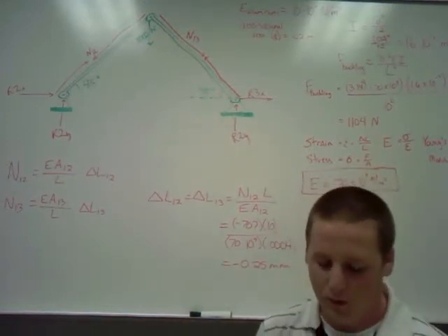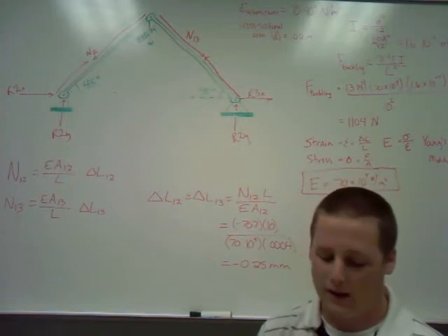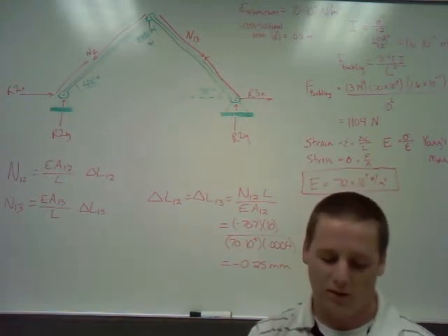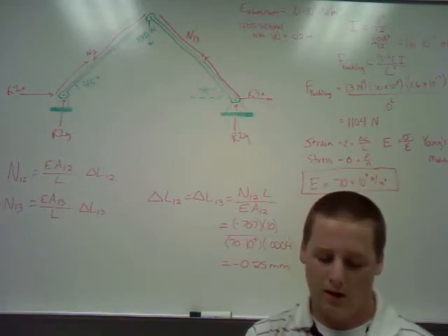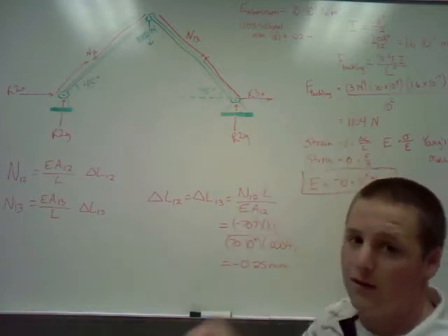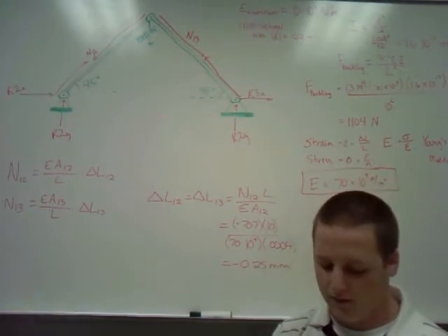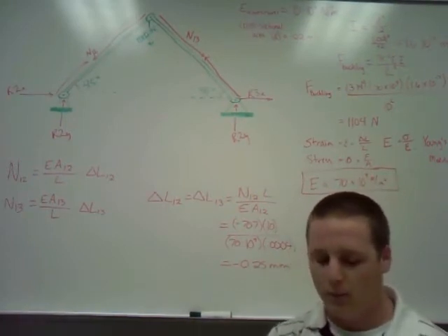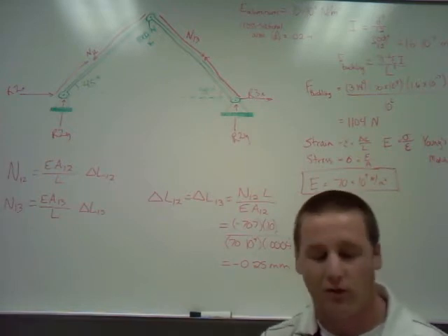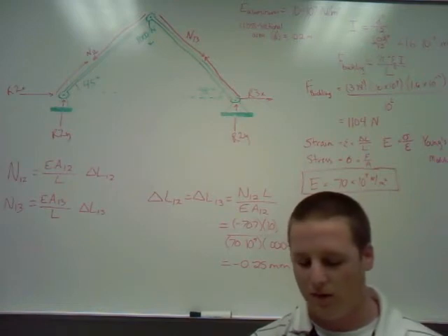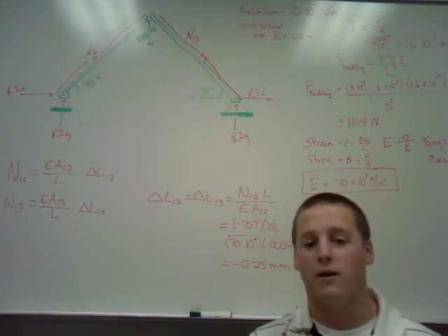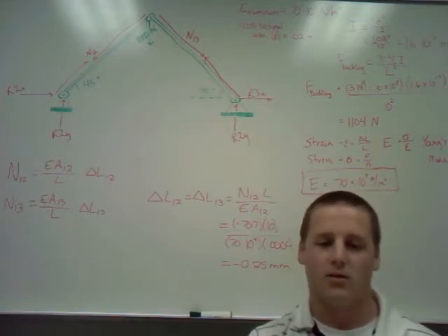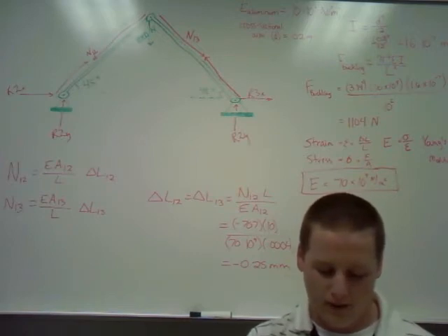So to solve for the buckling force, we use the equation force buckling is equal to pi squared times Young's modulus times the moment of inertia, all divided by length squared. So when we put our numbers in up here, we get 1104 newtons. For a previous problem, we know that the internal forces in the truss are 707 newtons, and since that's less than the buckling load we found, we will then know that the truss won't fail when the internal force is put on it.